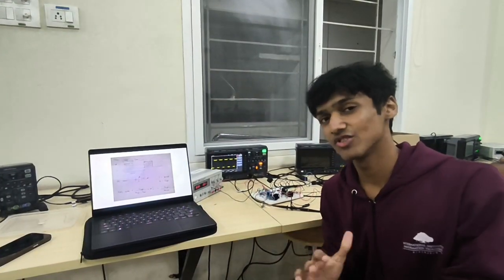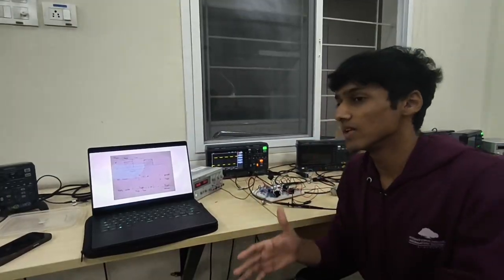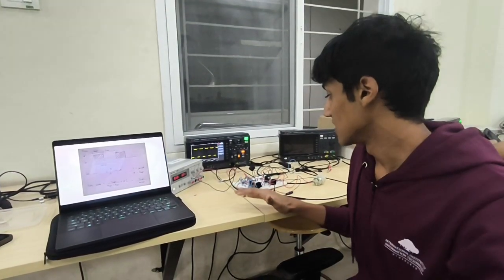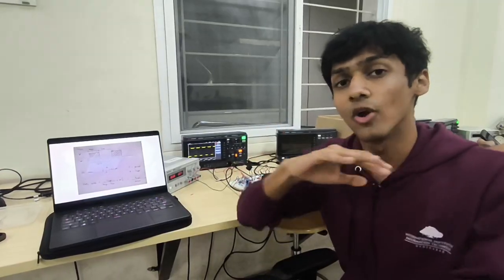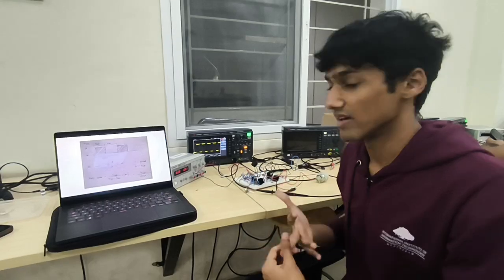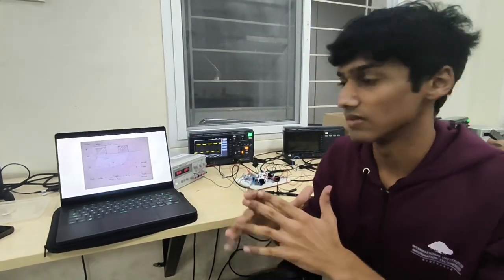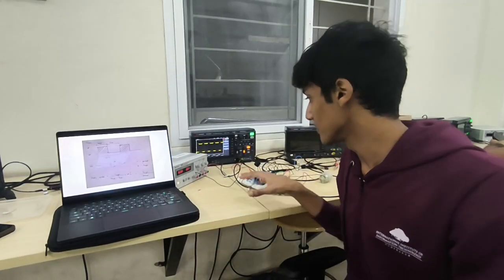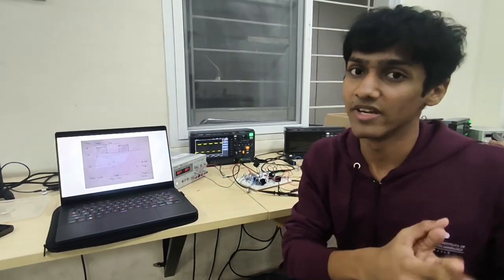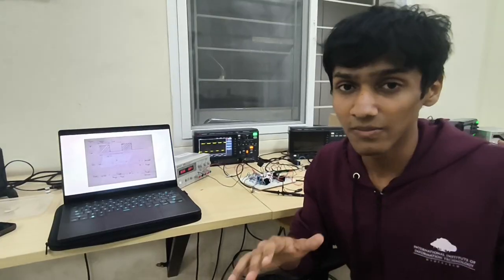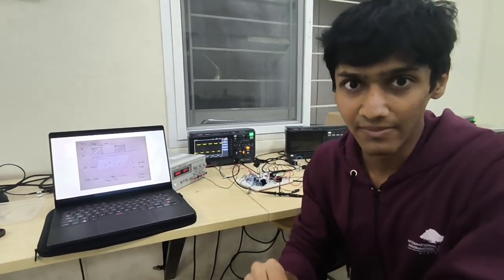Why did we specifically choose a PWM signal? What the H-bridge circuit sees on its face is a voltage, and if we send a pure analog voltage, there'll be a lot of power loss as heat, and the motor itself won't be able to overcome the torque using that voltage. So we use square waves, PWM waves specifically, which are consecutive on and off waves. We accomplish this using a 555 timer and a potentiometer.